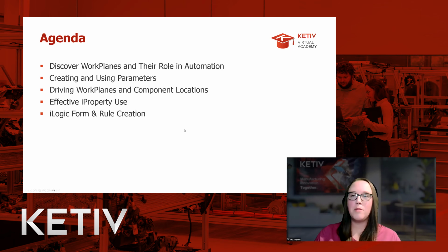Hey, everybody. Today we're going to focus on automating for assemblies and preparing for automation. The first thing that we are going to do, and if you joined the last time with the part automation, we're going to use WorkPlanes and then drive those WorkPlanes with parameters and iProperties and create a simple iLogic form and have a rule that is driven off that iLogic form.